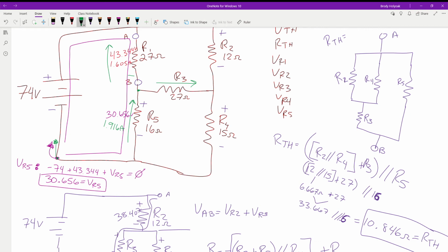So now that we have this, how much current do we have going through R3? Okay, we have 311 milliamps. How much voltage do we have dropping across R3? Which is where we got the 8.397 yesterday. So now, like I said, we can have confidence in this because we did already solve for this value yesterday. That was what I was jumping on, thinking we were only doing voltage.